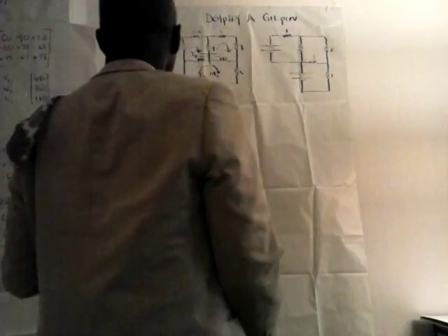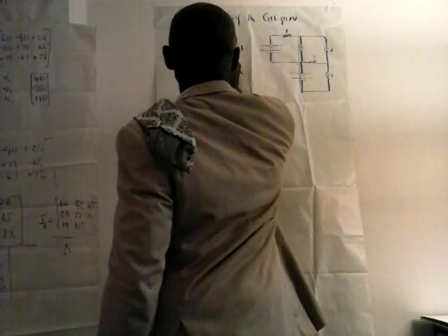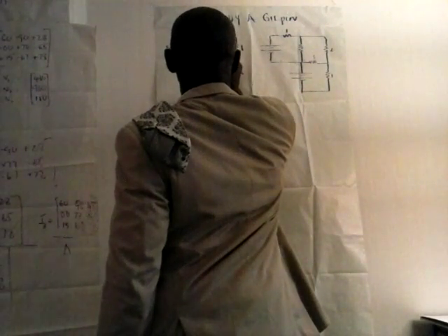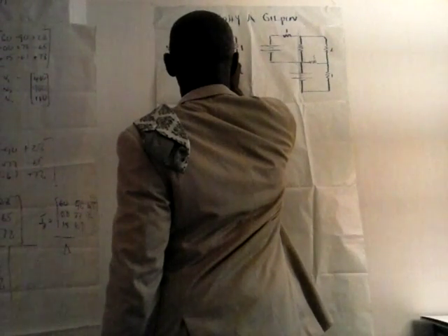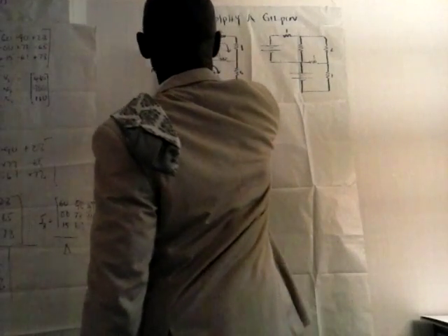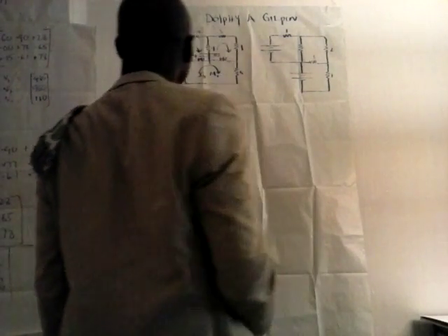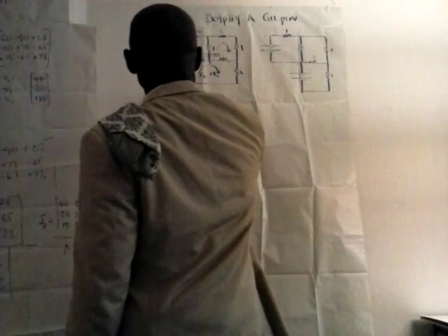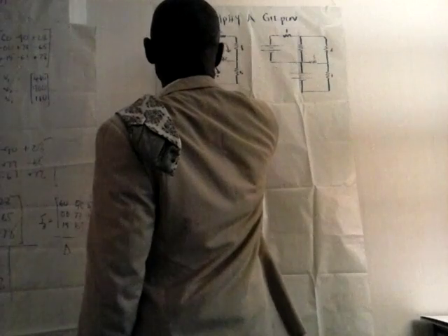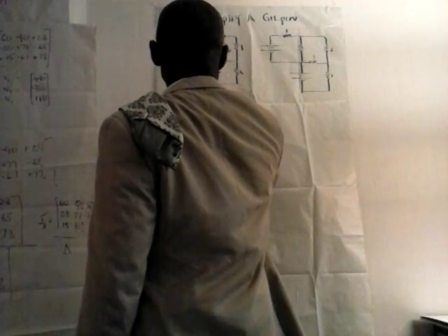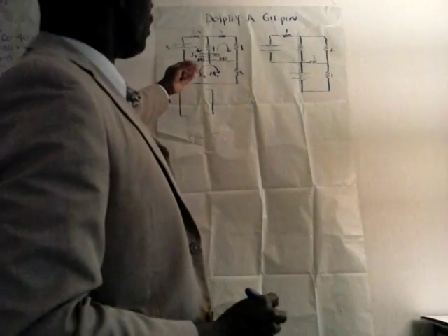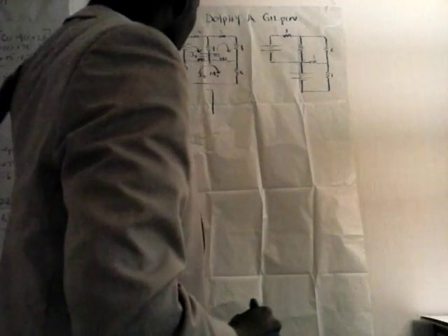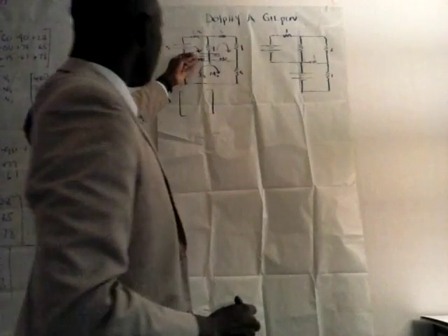And we say now that suppose this voltage was 10 volts, and this one was 5 volts. We say now that delta will equal the determinant of, and we're going to now put in the elements by inspection. So R11 would be the resistance in mesh 1.